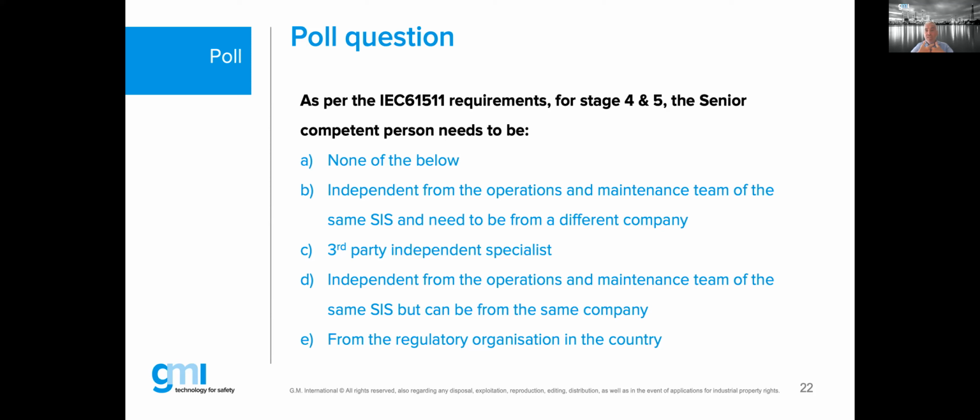For a SIL 1, an independent person can be from the same development team, but an independent person shall make the assessment. For a SIL 2, it's an independent department, maybe from the same company. But for any SIL 3 product that the manufacturer company is producing and releasing, the IEC 61508 clearly states an independent organization needs to make a functional safety assessment of that SIL 3 quality of that component.